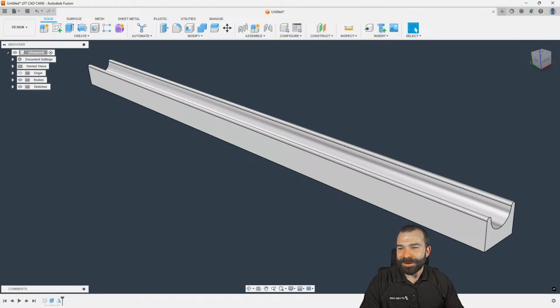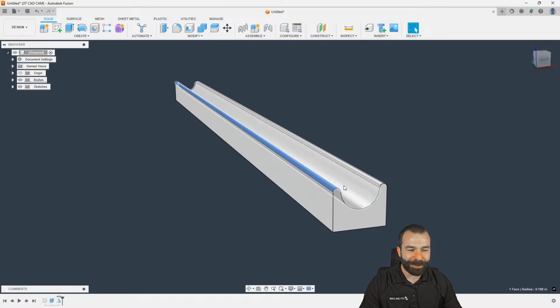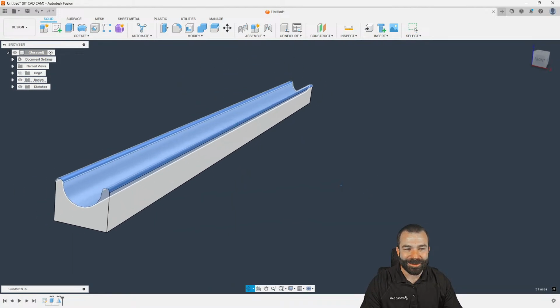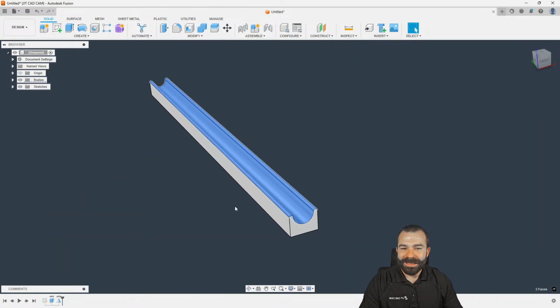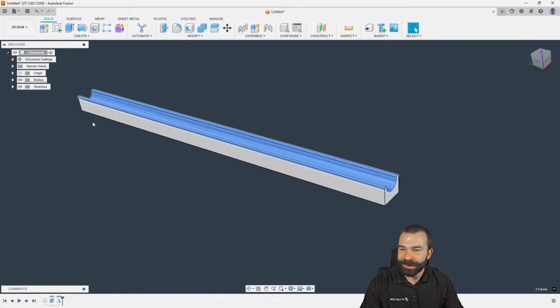But with that, I don't see anybody answering in chat. How would you go about, I'm just curious, you have to 3D basically these three surfaces at the top, right? So what the customer is wanting is to use a 3D toolpath. This might also be a little bit too long for their machine, which is going to be the little trick that I'm going to show you with how we can use boundaries and maybe even toolpath trimming.